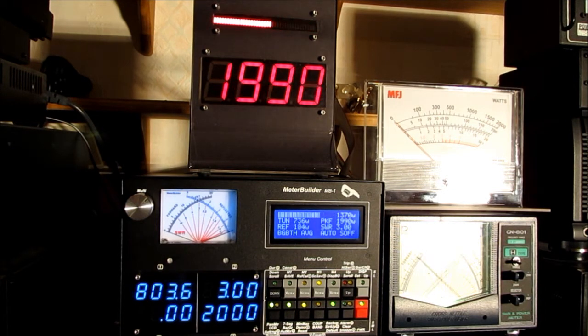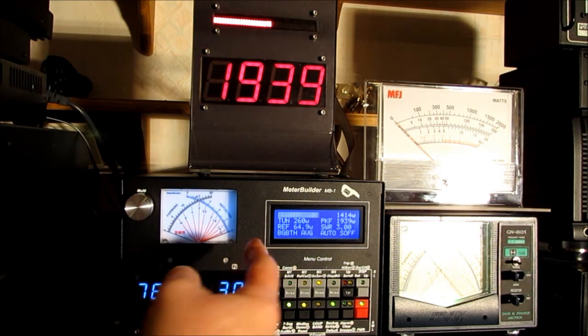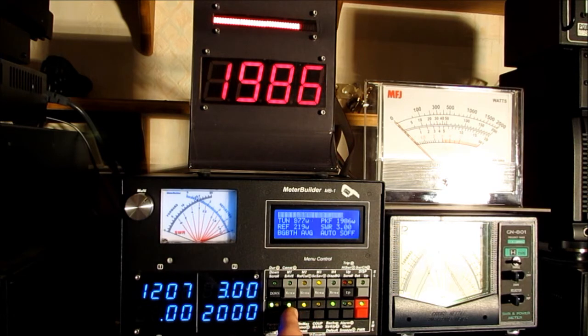And if that currently encountered signal increases, as it just did a little bit, the Automax full-scale value will increase, so that you're guaranteed that you'll never go into an overrange. It also guarantees that you will always have maximum resolution. At any point, if you change your power, let's assume you switch from linear operation to barefoot, and you've maxed out at the linear power, you can always reset the bar graph full-scale value.